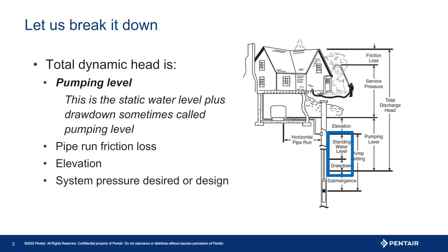A question often asked is, do you use the full drawdown even if you are using a fraction of the production? And I would answer yes. Always plan for the worst case scenario. You never know what could change in the well condition. Remember, pumps move water but cannot create water. Calculate using the full drawdown.